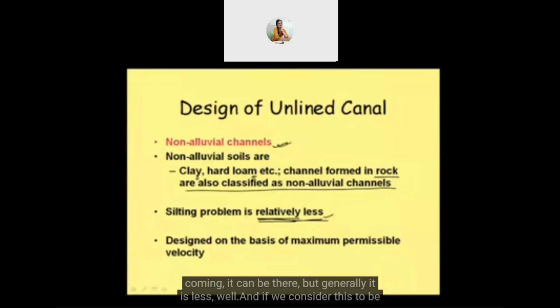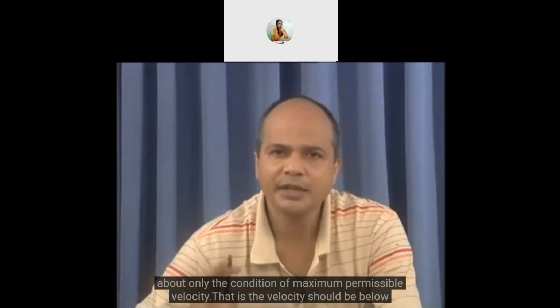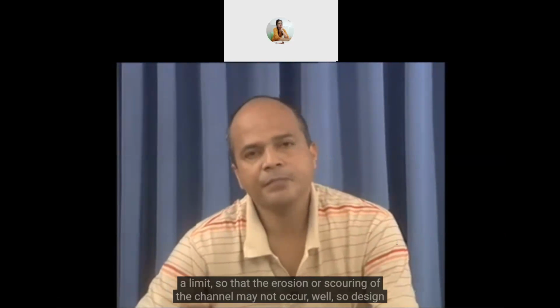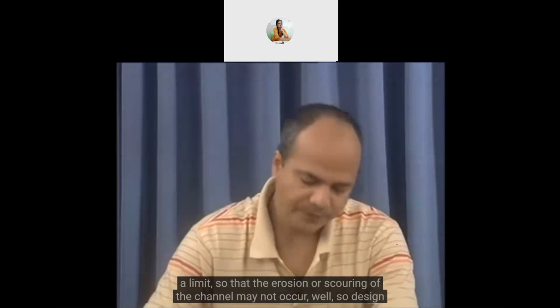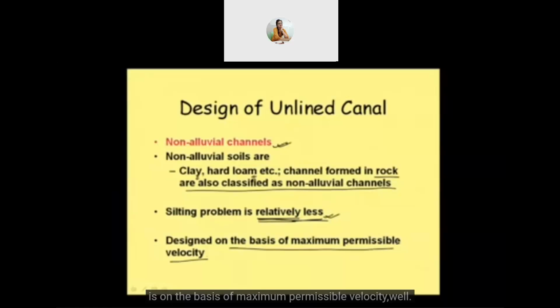Well, and if we consider this to be less, then we forget about the condition of minimum permissible velocity. Then we think about only the condition of maximum permissible velocity. That is, the velocity should be below a limit so that the erosion or scouring of the channel may not occur. Well, so the design is on the basis of maximum permissible velocity.